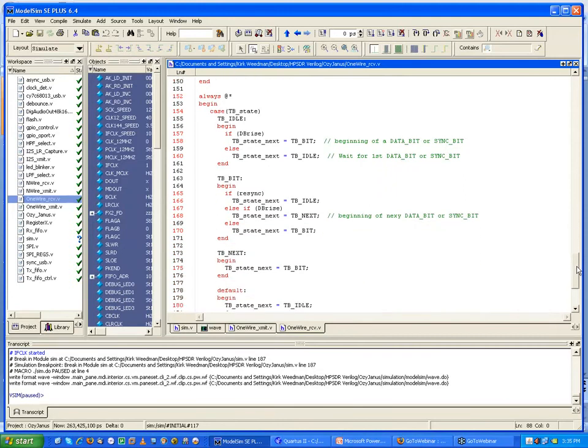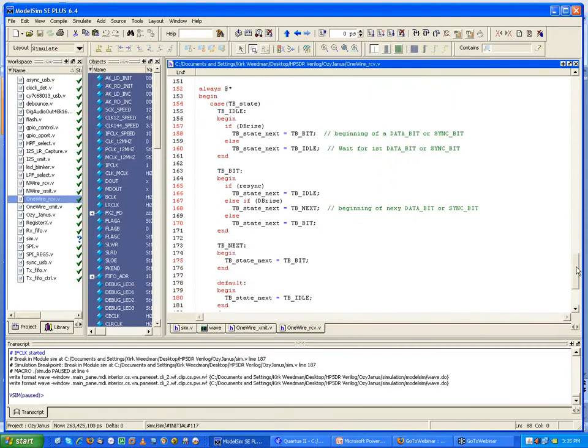Then the next always block that I have in here, you'll notice I said @ star. I could have a sensitivity list where I list everything, and that would be in accordance with the 1995 Verilog standard. This will work according to the new 2001 standard. As early as last year, though, I did see one case when I was using the Xilinx ISE tools, that it wouldn't take this for a particular thing that I was doing that had to do with some generate statements, which are part of the new 2001 Verilog standard.